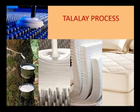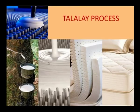Latex is nothing but a liquid coming out of a plant, and that liquid has the isoprene unit. Isoprene is the monomer unit and it is polymerized. It is called polyisoprene. That polyisoprene is present in your rubber latex. That liquid rubber is taken, it is processed, and you add additives to it, namely, as I said before, the zinc oxide, gelling agent, and secondary gelling agent.